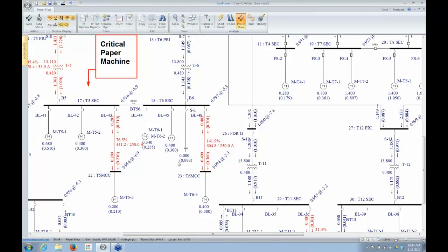The other thing to note is this is not exactly 1 megavar. That's because my voltage is slightly below 1. So a capacitor is a capacitor. It's not a megavar machine. It's only its rated VAR output at its rated voltage. So as the voltage goes up, the megavars increase. As the voltage goes down, megavars decrease.